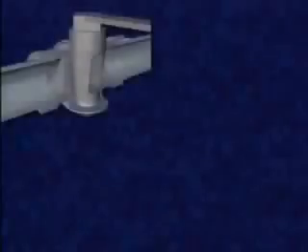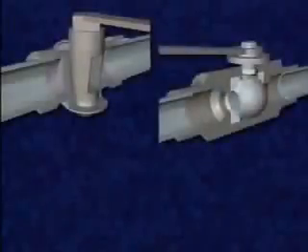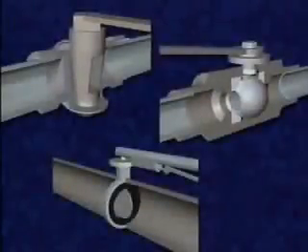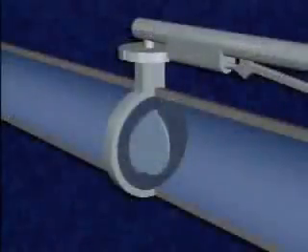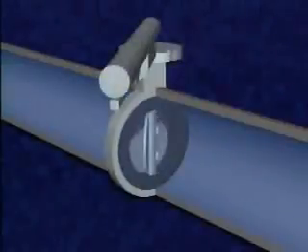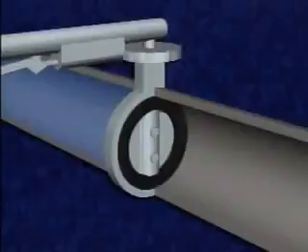In this part, we'll look at plug valves, ball valves, and butterfly valves. A distinctive feature of these valves is that none of them has a disc that moves up and down from the valve seating area. Instead, each type has a disc that rotates. The rotating disc enables the valve to be opened and closed more quickly than many other types of valves.